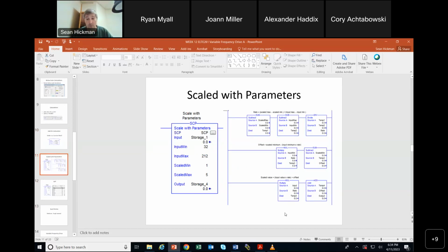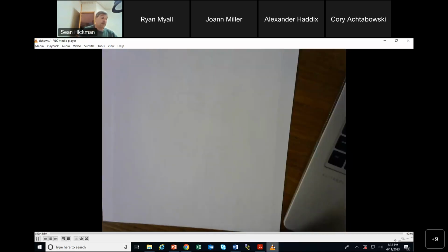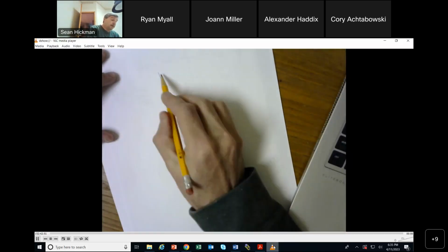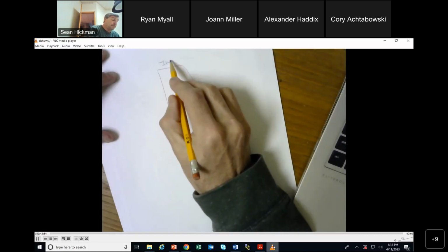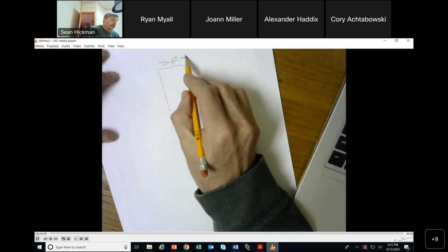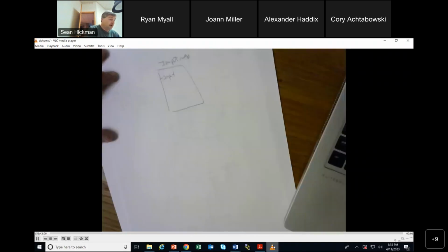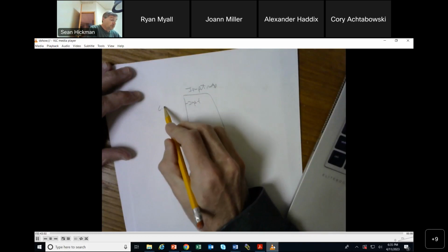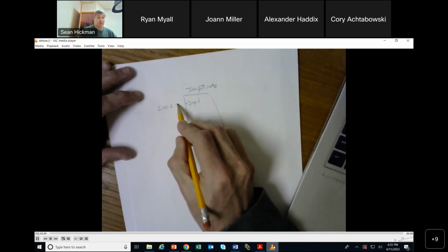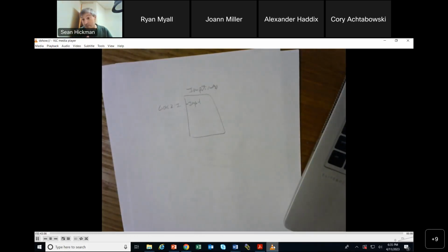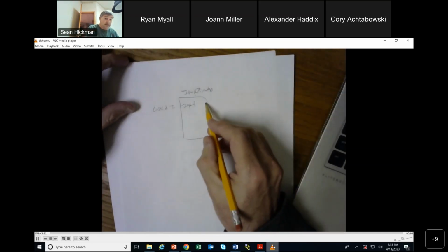One of the things you might see is an add-on instruction for IO mapping. Some people map with that. They put this right here, and it might say input map, and here it might say input. Your input might be Local:2:I, so you put your Local 2 wherever your inputs are. Then it would map them.